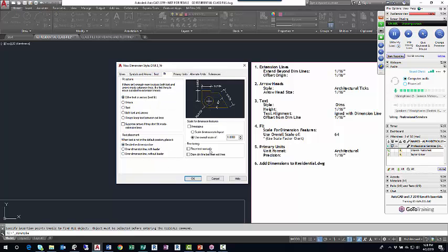The Fit tab governs fit options, text placement, stuff like that. I'm not going to change anything here except the use overall scale of, and you can see here at step 4 in my handout, fit will use an overall scale of 64, and that comes right from the scale factor cheat sheet. Swipe over that 1.0000 and type in 64. Don't try to use the up arrow. I don't even know how long it'll take you. All right, so we go 64 as the use overall scale of.